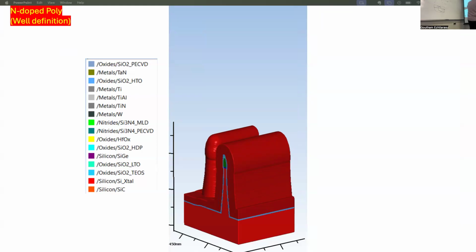I knew you would ask that question. Yeah. So basically, the P fin is touching the N polysilicon and the N fin is touching the P polysilicon. Now when you anneal this, they diffuse into the fins and dope them, right? They diffuse at the same time. Yeah, because I'm annealing it together. What do you mean mobility will be? If the mobility is different, I just dope these polys differently.